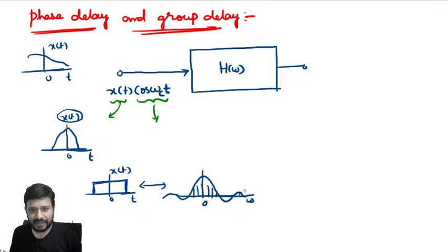And these are high frequency contributions. So the low frequency portion is predominant here, which means with low frequency components I'll get the shape of this rectangular pulse, and by adding high frequency components the sharpness of the signal increases. Or we can say that there are an infinite number of frequencies. How many frequencies are present in this rectangular pulse? Infinite number of frequencies.